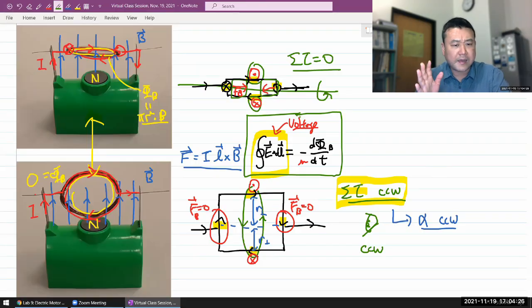And this is again why it's dangerous to just stop the motor, because if you just stop the motor, the amount of current that can flow through the coils is no longer limited by anything other than the resistance of the wire. And if you have a very low resistance wire connecting one end of the battery to the other, that's a short. It can draw a lot of current, and that's dangerous. So simply stopping the motor cold is not something that you should do. While the motor is running, it's perfectly safe because this induced voltage will oppose the applied voltage, limiting how fast it can spin and how much current it eventually draws.